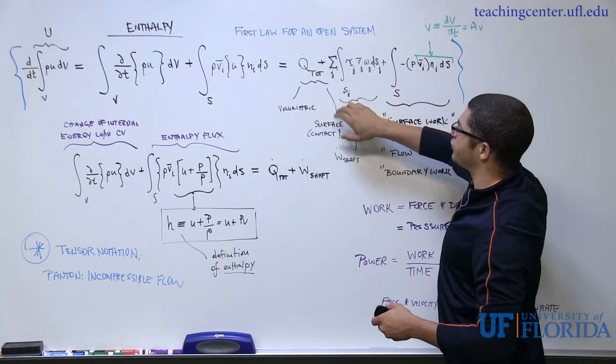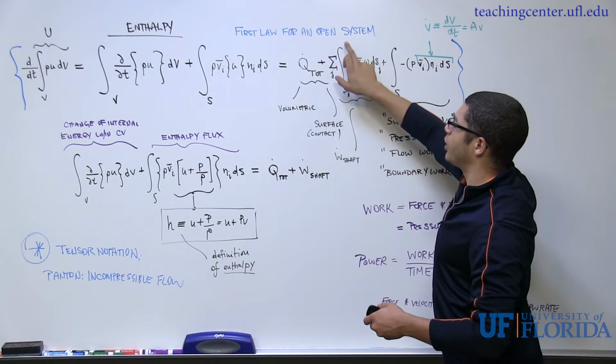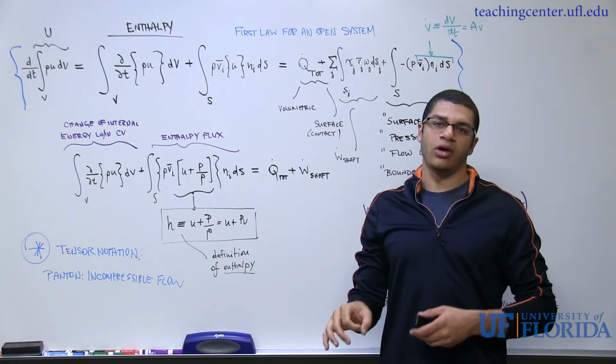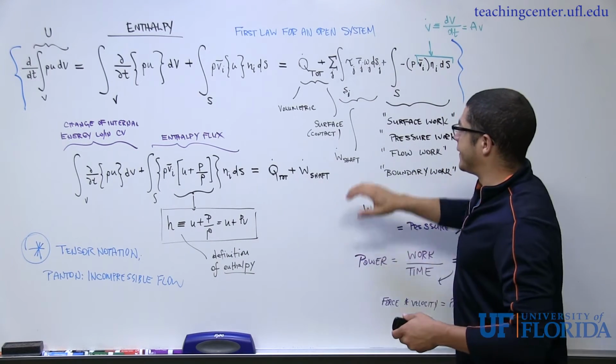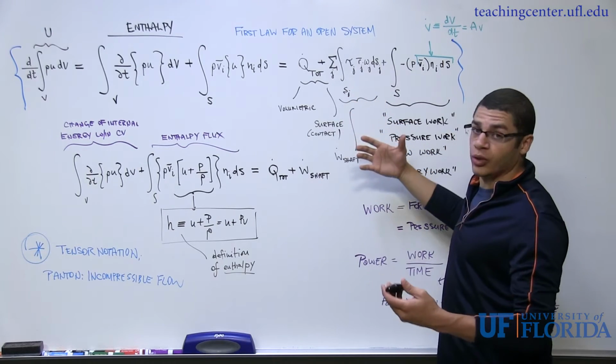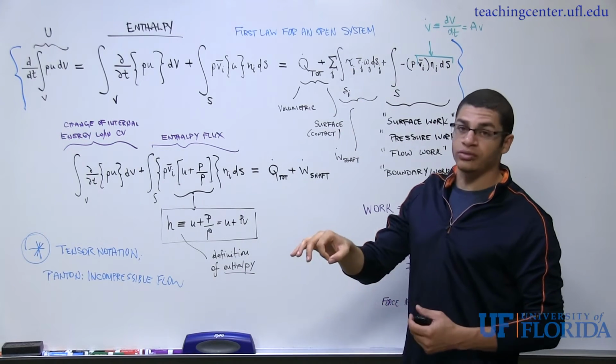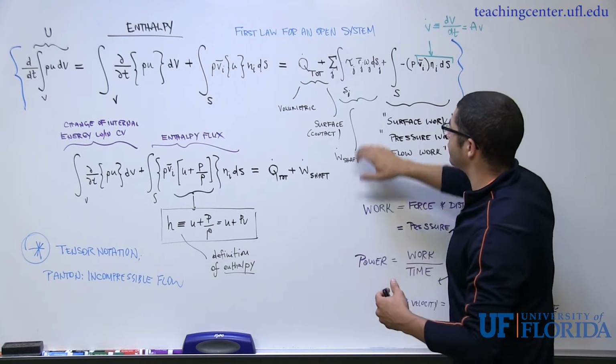So a discrete summation, and then at each j point, I'm going to be integrating over S sub j, which is going to be the cross-sectional area of the shaft. And what I'm concerned with within that cross-sectional area is the shear stress distribution on the cross-section of the shaft.